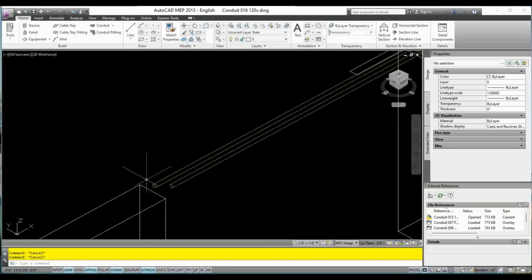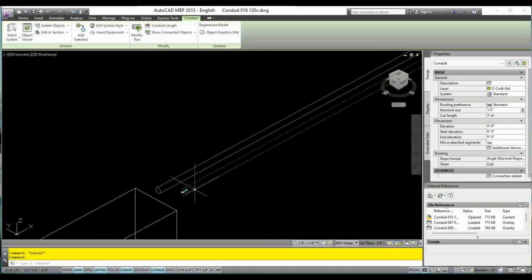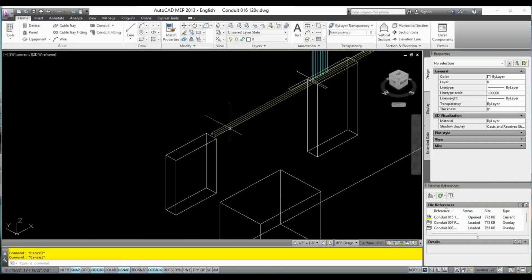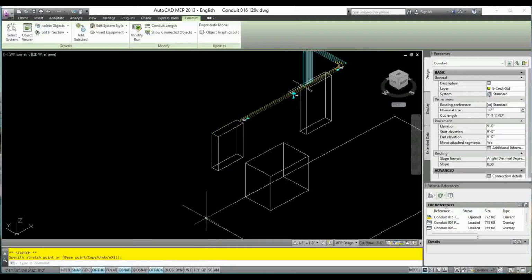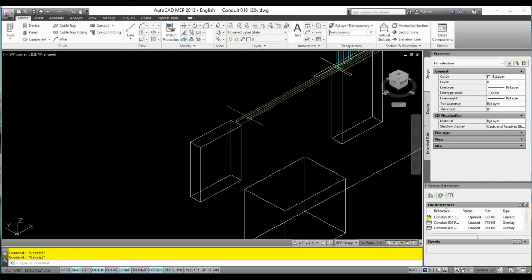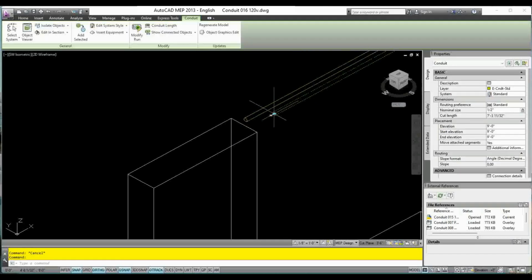So how do we fix that? What you do is you grab the pointer and ask, what do I want to run it up to? I'm going to run it up to the end of that pipe. Well, you could also run it up to some other object. Let's say I want to make it only as far as the edge of the transformers. I'll click that. See that? Or I can make it to the edge of the room. Well, now we were pretty close. That means we're going to be out of the room if I match this conduit right here.